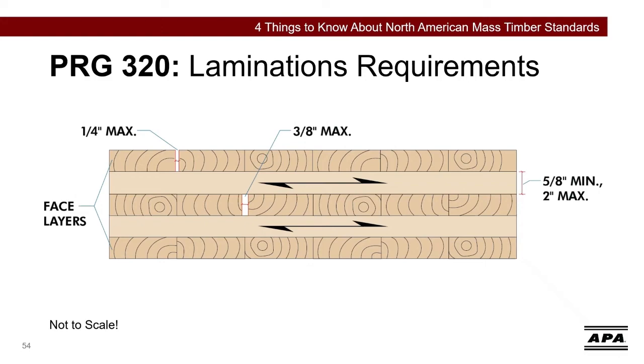Note when edge joints of laminations are not bonded with an adhesive or not filled in with filler, small air gaps are common per CLT. These gaps will affect the air tightness throughout the CLT thickness, and the effect will depend on the number of CLT layers and actual gap size as manufactured.